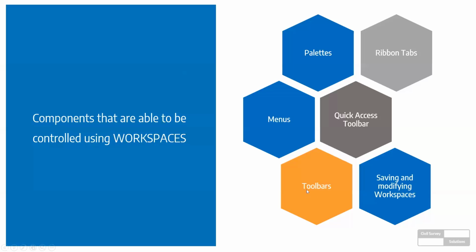We'll also be looking at toolbars. Toolbars are sort of one of these old tools that have been around for years. Not a lot of people use them, but you might find that the O-Snaps toolbar is very handy. So you can just click on an O-Snap and that snap becomes active. So we're going to display probably a couple of toolbars during the session, and then we'll move on to saving